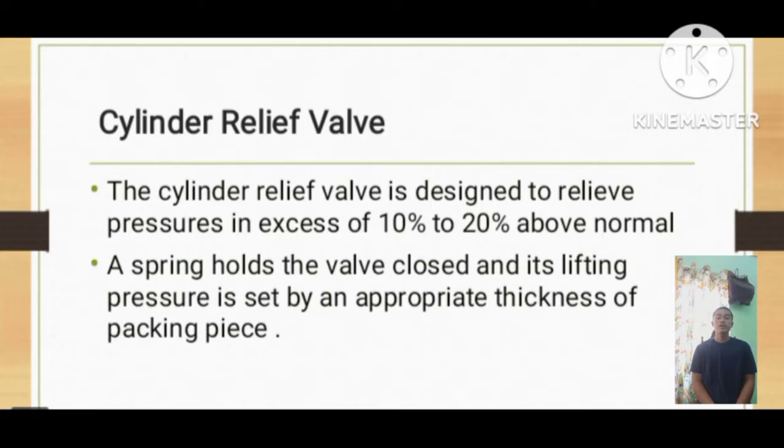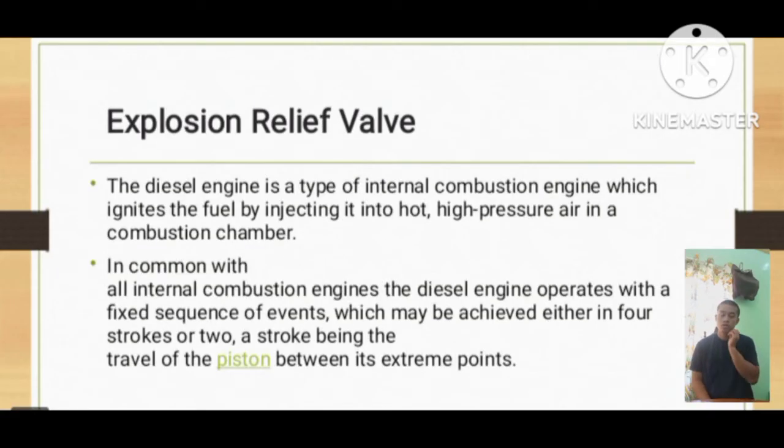Third is incorrect camshaft timing, chain breakage or governor fault, especially in heavy seas. Fourth is a badly leaking fuel injector through a lost nozzle or enlarged injection holes. Fifth is water leaking into the combustion chamber. Last is scavenge fire. So what is an explosion relief valve?